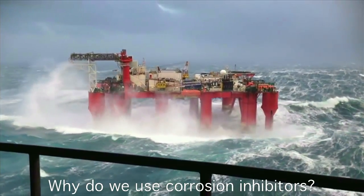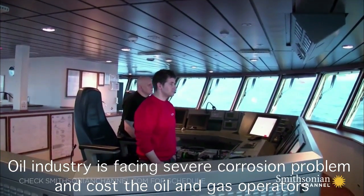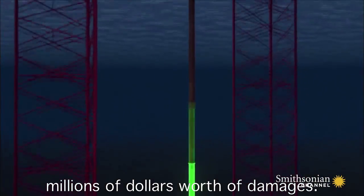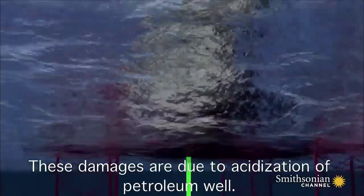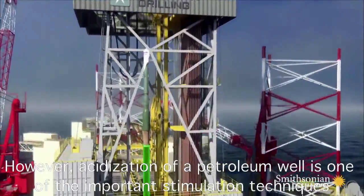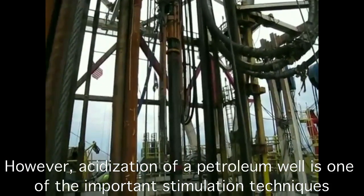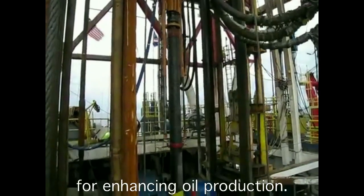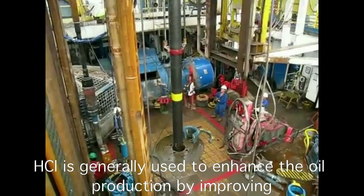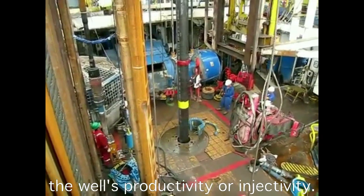So, why do we use corrosion inhibitors? The oil industry is facing a severe corrosion problem that costs oil and gas operators millions of dollars worth of damages. These damages are due to acidization of petroleum wells. However, acidization of a petroleum well is one of the important stimulation techniques for enhancing oil production. Hydrochloric acid is generally used to enhance the oil production by improving the well's productivity or injectivity.